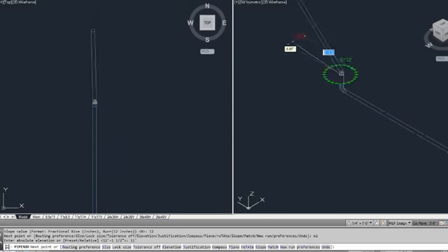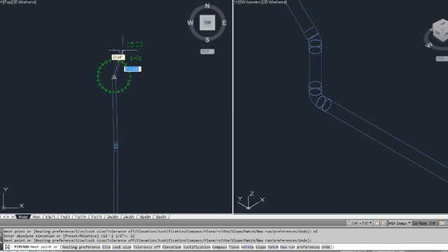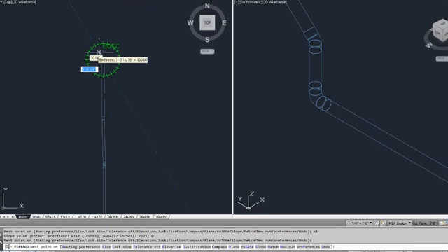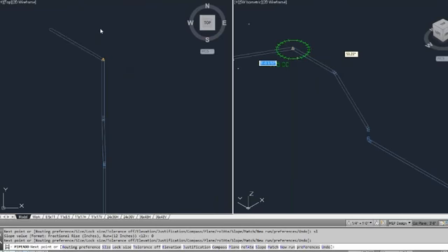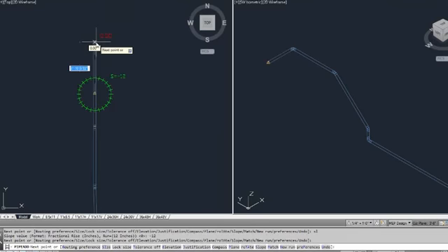So now if I say elevation 11 feet and went up, slope of 12, I said 45 degrees, it didn't go up at 45. Let's try that one more time. When I run it like this, you can see that I'm sloping up. I can then change my slope back to 0. You can see that it put it back in straight, and then I can change my slope again back to minus 12, put in a small little slope piece of pipe, and then change my slope back to 0.